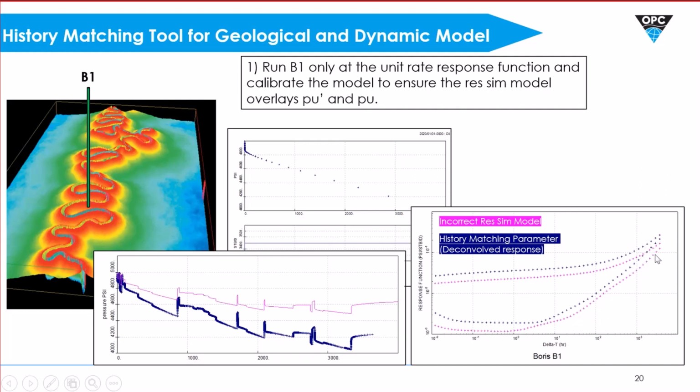But if I use straight line analysis on this point and the blue data for the correct match, it can tell me by how much off it is. So for instance, if this told me it was 50 million stock tank barrels of oil, but it should have been 34, it tells me by how much I need to reduce the stock tank barrels of oil by. Likewise for the permeability. So if I fix these two things, I can run it again. Then I can check what the skin at the well is, and I can do all this iteration.